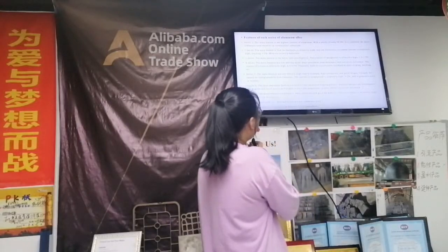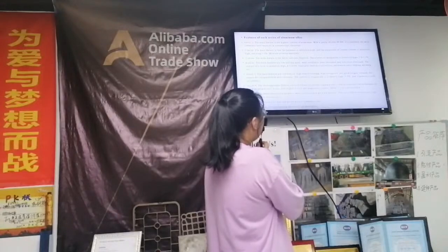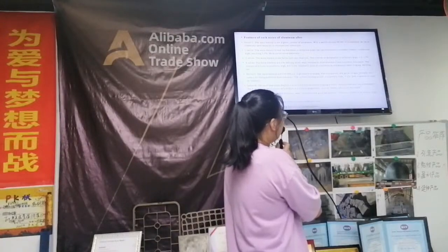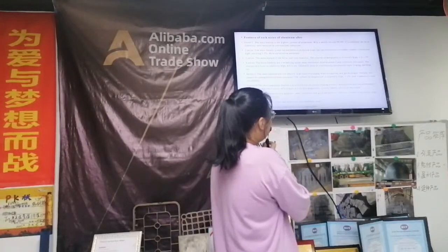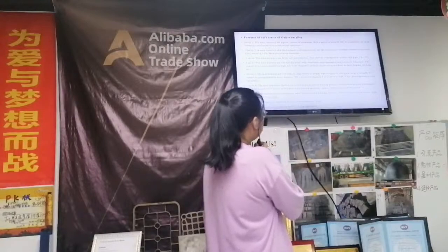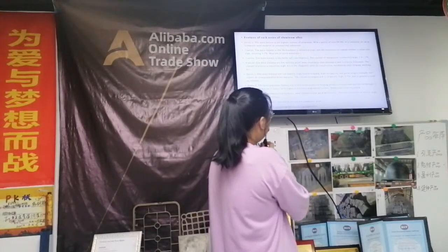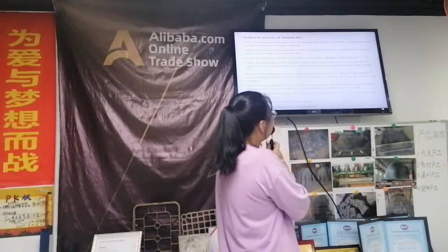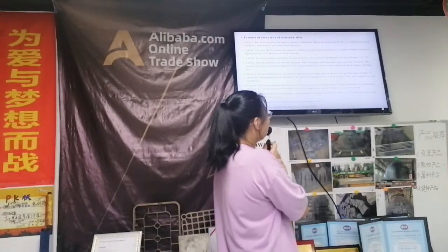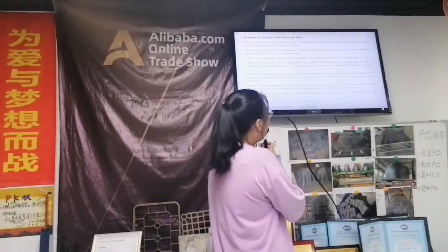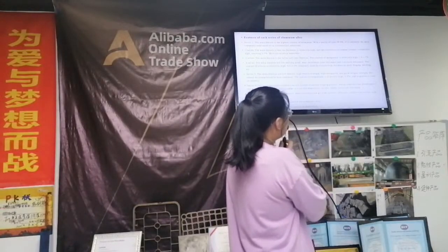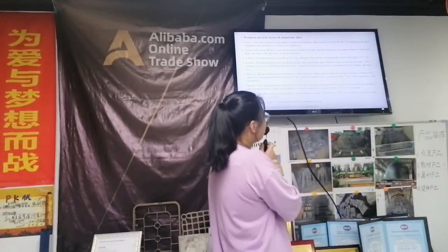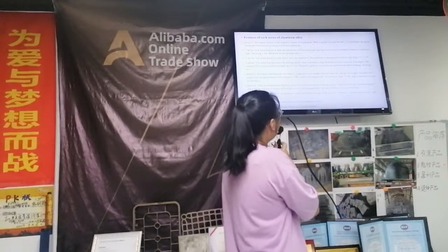Four series: the main features are low melting point, wear resistance, heat resistance, and corrosion resistance. The content of the silicon is relatively high, 4.5 to 6.0%. Generally used in construction, mechanical parts, forging, welding.